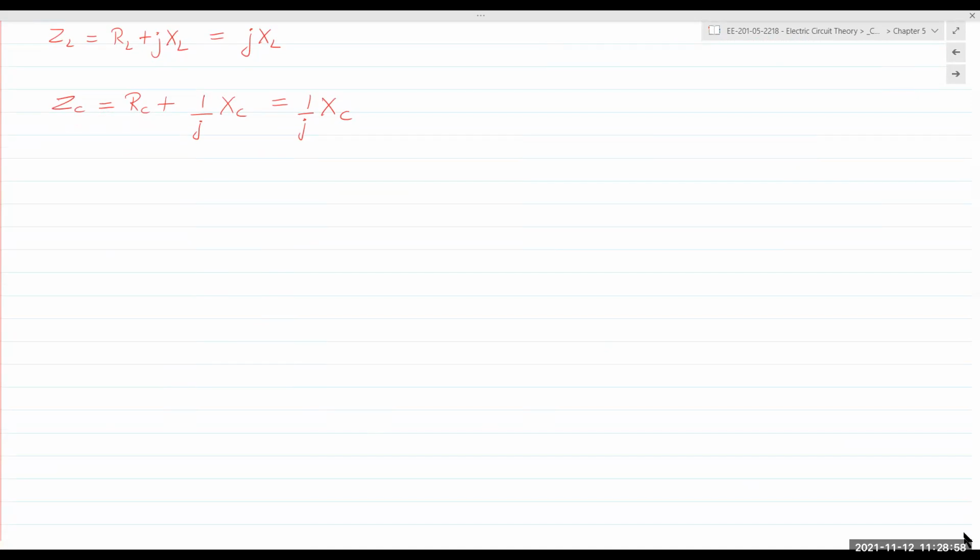And the distance between that crossover point and time t equal to 0 gives us the phase. If it crosses the x-axis at time t equal to 0, then the phase is 0, right? If there is a shift or a difference between time t equal to 0 and when the waveform crosses the x-axis, that is defined as a phase shift.